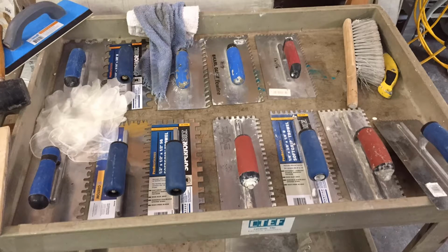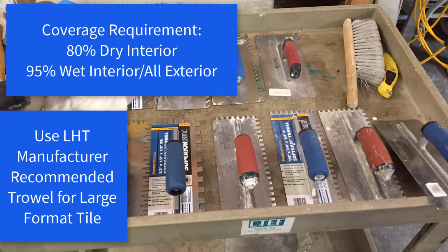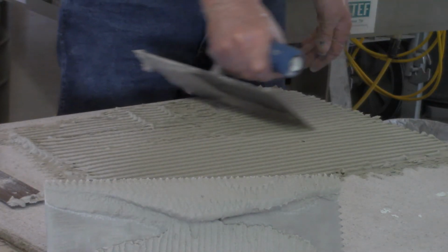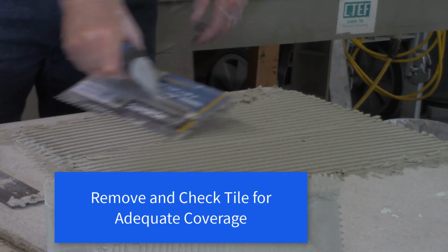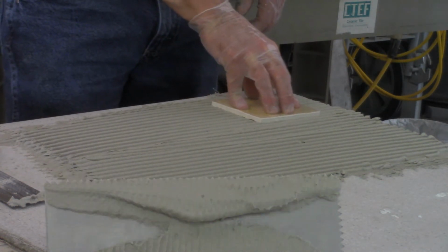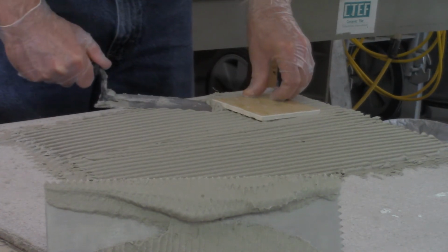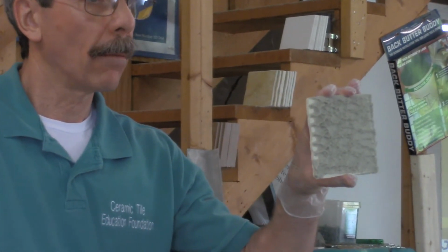Determine the proper trowel size and setting material to maximize the coverage and integrity of the tile job. For large and heavy tiles, use the trowel recommended by the LHT mortar manufacturer. For smaller tiles, a 1/4 inch by 1/4 inch trowel may be a good place to start. But removing a tile is the only way to be certain that adequate mortar coverage is being achieved. Always refer to manufacturer's recommendation for proper trowel use and setting material requirements for the substrate and type of tile.